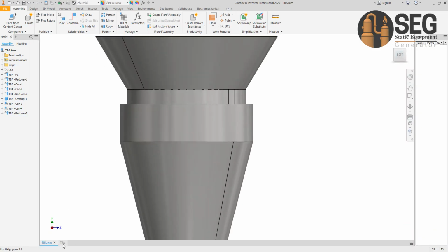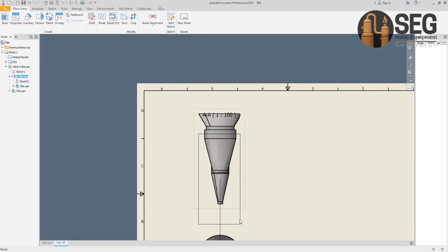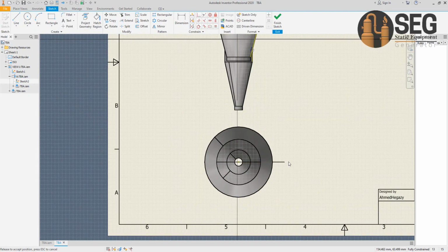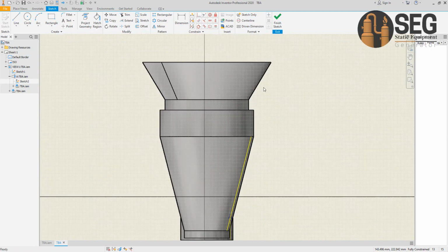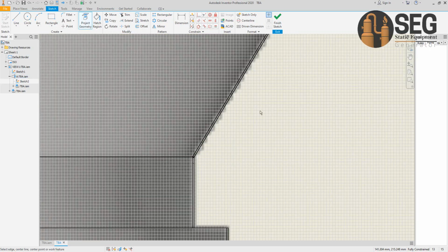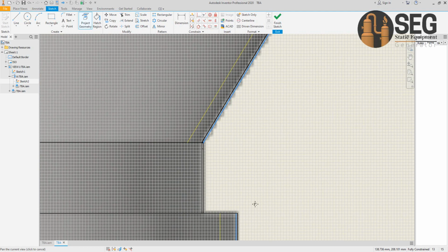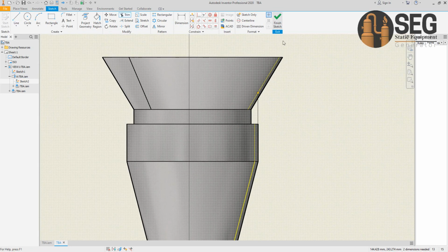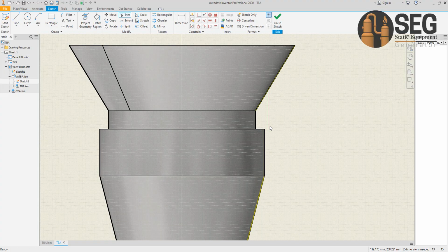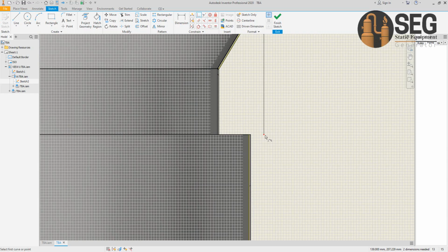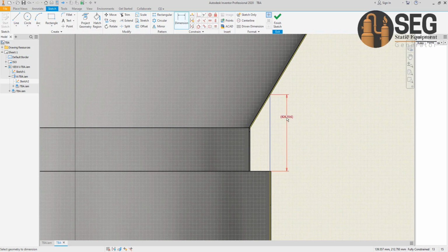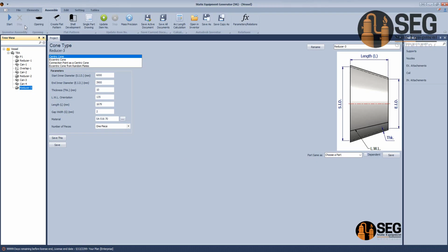So let's come back to the drawing and make a new sketch. Select the same sketch here. Let's extend this one, and let's project this line and that line, and from here let's extend to meet, and let's measure this line length, and now let's add overlap.